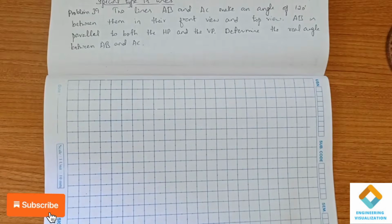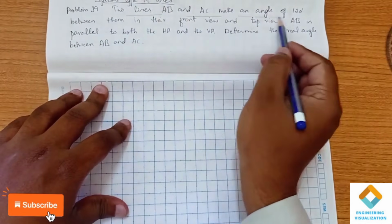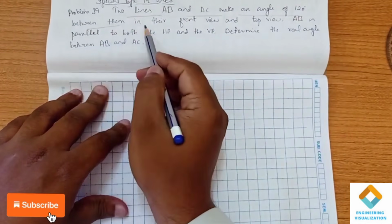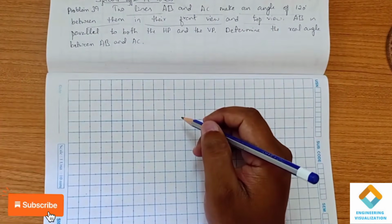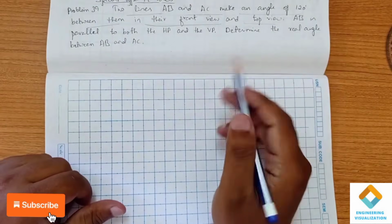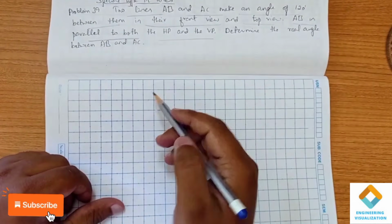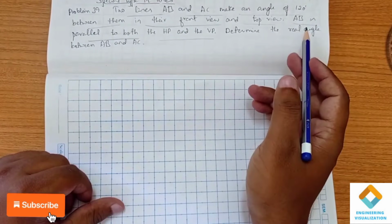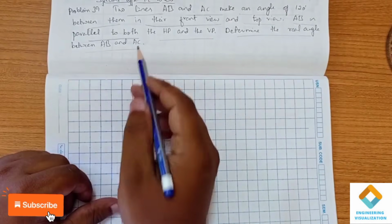It is one of the special type of problems in lines. It is problem number 39 from the CAD solution book. So you can see in this problem there are two lines given, AB and AC, which make an angle of 120 degree between them in their front and top view. AB is parallel to both HP and VP. Determine the real angle between AB and AC.